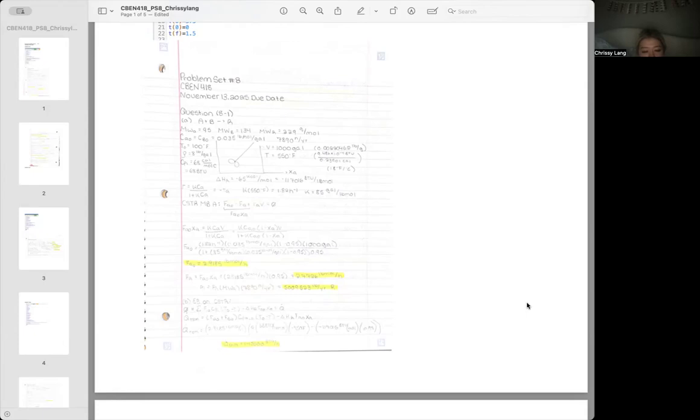For the energy balance, I applied the steady-state CSTR heat removal equation, which includes the sensible heat needed to bring the feed from 100 to 550 and the large exothermic heat of reaction. By substituting in F_A0, Cp, ΔH_R, and X_A, I solved for the total heat that must be removed under the original conditions and scaled up.